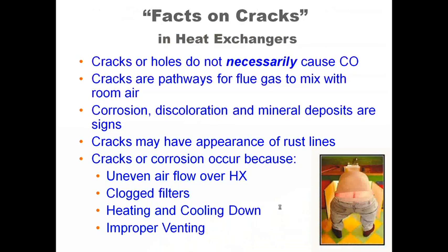All right, some facts on cracks. Just because you have a crack or a hole in a heat exchanger does not necessarily cause the CO. It could, it absolutely could, but it doesn't necessarily mean it will. So you can't tell a homeowner, oh, you got a crack in your furnace, you're going to get CO poisoning and die. Well, no, that's not necessarily true. What it is, is a pathway for flue gases to mix with room air. And it's also, obviously, could potentially make the CO in the appliance. So again, any crack is a failure.